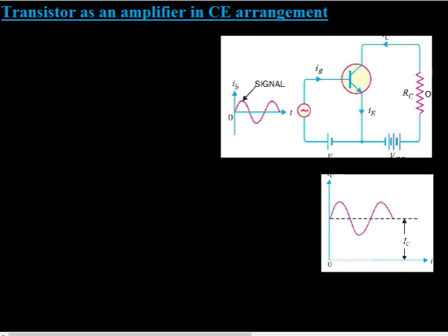Good morning. In the previous lectures, we have seen different transistor connections, namely common base, common emitter, and common collector transistor connections. Out of these three, common emitter is the most commonly used one because of its high current gain, voltage gain, and power gain, and also it provides a moderate output to input impedance ratio. So in 95% of transistor applications we will use common emitter transistor connections.